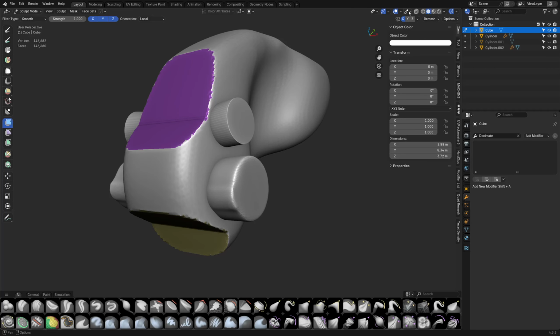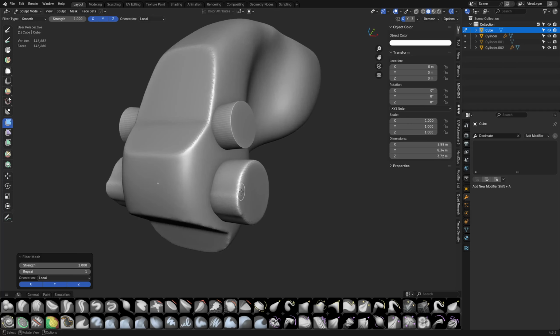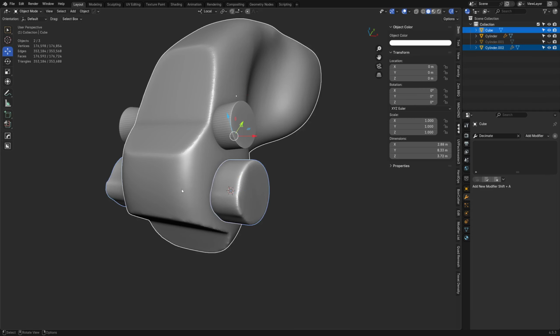And we're going to hide those face sets for now. Face sets might be useful for converting into materials and doing quad remeshes later. It's not quite the ZBrush workflow with like Z remesher, but it's kind of close, and it's something I still got to work out some bugs with, but it's getting better, especially with Vulkan and denser geo, I think. But the main thing here is that if we want to do booleans, I'm going to be using auto booleans usually with the bool tools add-on. So Control Shift B with the bool tools add-on.